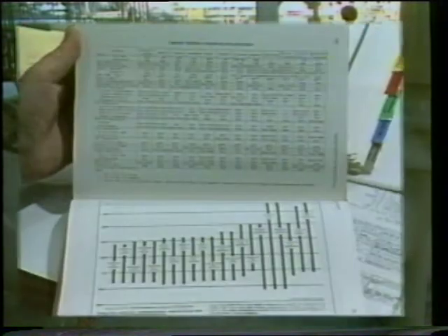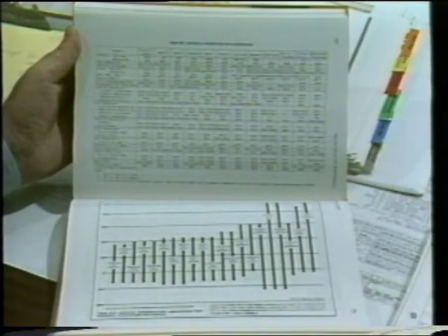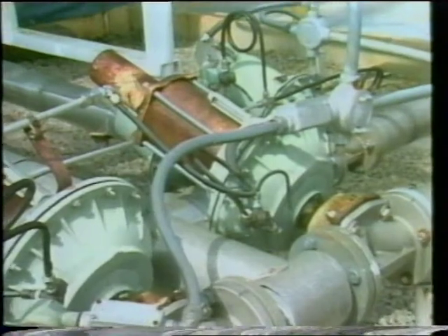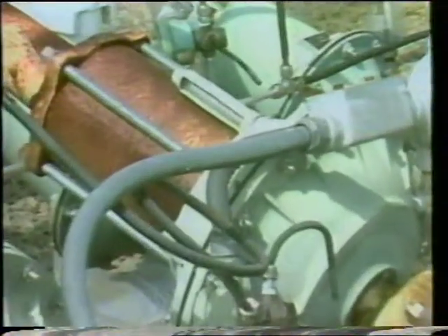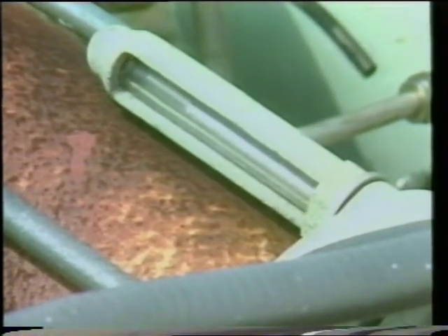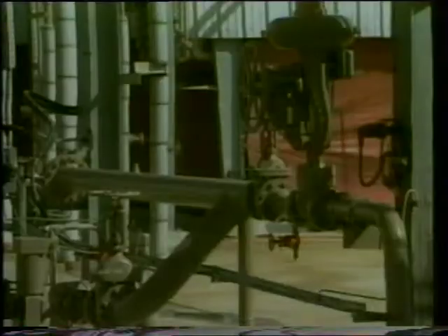Factors such as valve stroke may require the use of a piston actuator or a rolling diaphragm instead of a standard diaphragm actuator. Environmental factors such as temperature and atmospheric contaminants must be considered for their effects on diaphragm materials. Of course, what the actuator response must be on a loss of actuating power, whether pneumatic, electric, or hydraulic, must also be kept in mind.